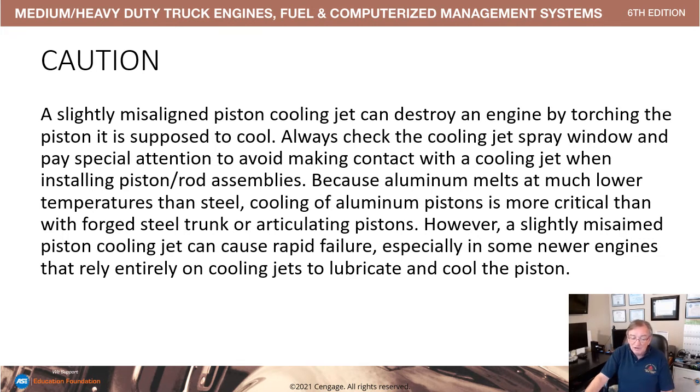So pay attention to the spray jet window and to it making contact with the piston when you're installing your assemblies. Because aluminum melts at a much lower temperature than steel, cooling of aluminum pistons is more critical than with forged steel or articulating. However, a misaimed piston cooling jet will cause rapid failure in newer engines, regardless of the material that the piston is made of.